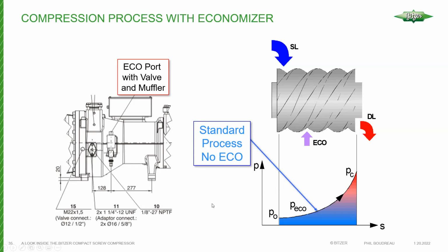And in my opinion, when you get into really high compression ratio, well, we'll call them freezers, or anything operating, compact screw compressors are not really low temp compressors, but we'll say medium temp, and then the lower temp end range of the medium temp, economizing just makes more and more and more sense.